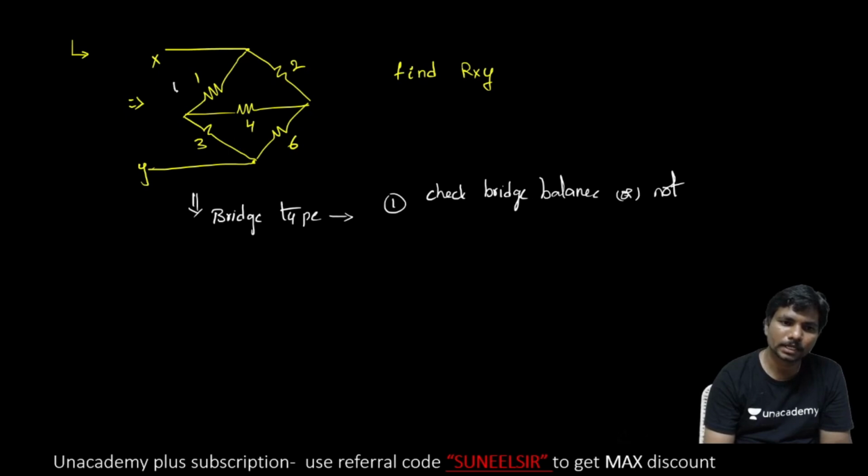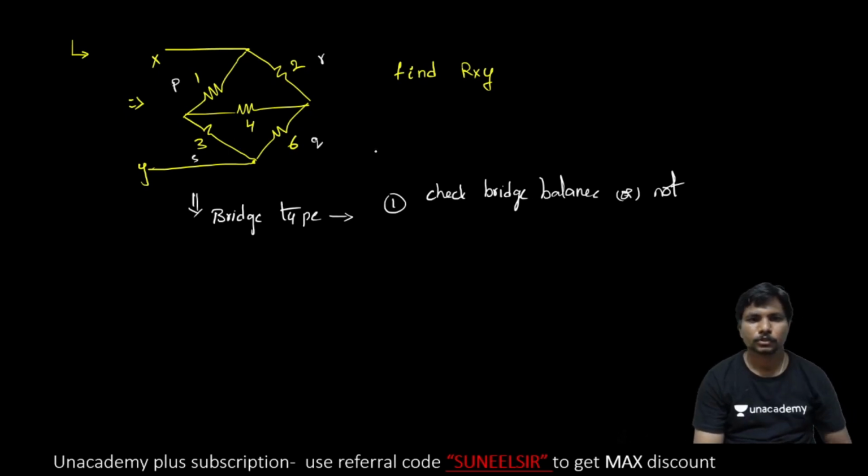How to check? Is the product of opposite arms equal or not? So PQ is equal to RS or not. 1 into 6 is equal to 3 into 2. So 6 is equal to 6. So the bridge is balanced.